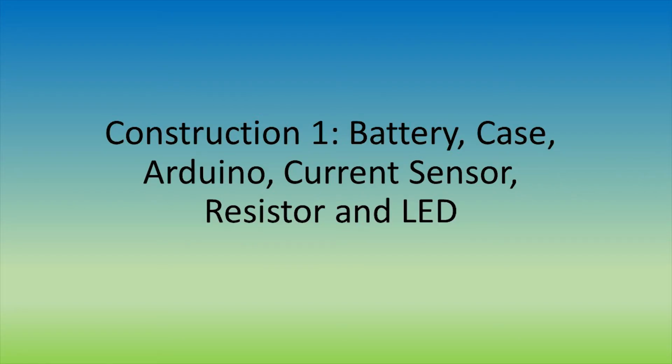Now you're going to start your first construction of the device. You did most of the wiring from Activity 5, but there are a few things you still need to do. First, you will be attaching the battery holder to the case and sending the power cable through the larger of the two holes. Next, replace the resistor with a resistor with a value between 2 kiloohms to 5 kiloohms. Lastly, disconnect the 9-volt battery wires from the circuit.